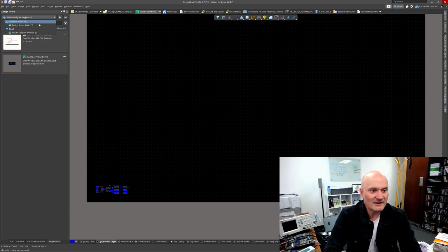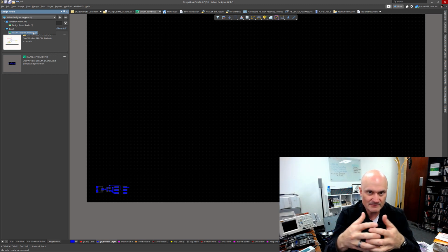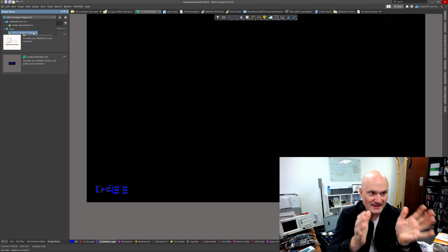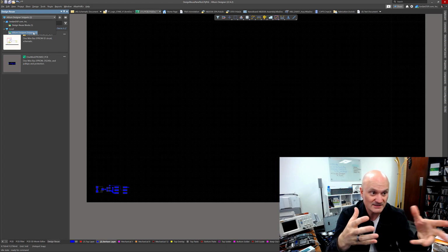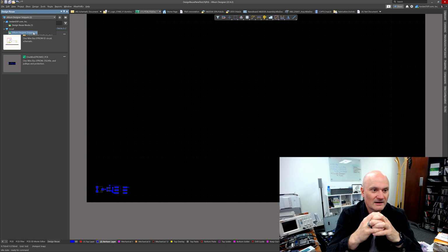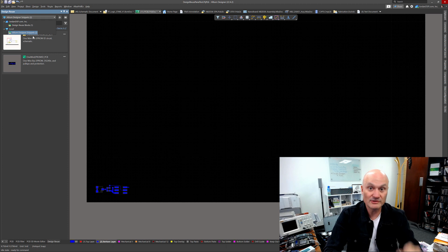And you can't make a design reuse block which retains the schematic and linked PCB parts together, at least as far as I can see in this current release of this feature, you can't do that locally. The only way to do that is to use an Altium 365 workspace or Concord Pro server and save your reuse block there, as I showed in the last video. So if you haven't seen that video, go back and watch it.